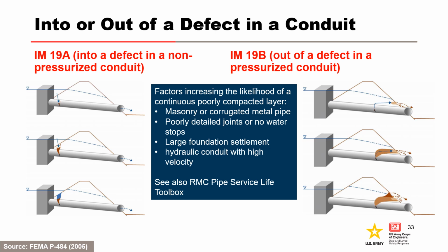Depending on the location of the defect, a sinkhole may form below or above the reservoir level. If it forms to exit into the reservoir, the PFM may progress by hydraulic fracture along the exterior of the conduit, resulting in piping failure along the conduit.